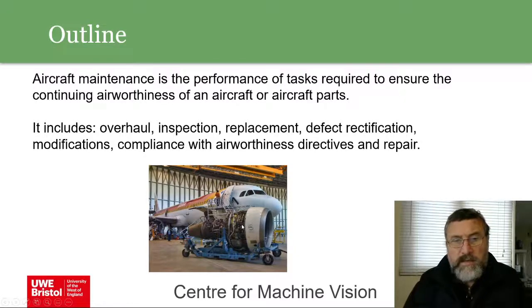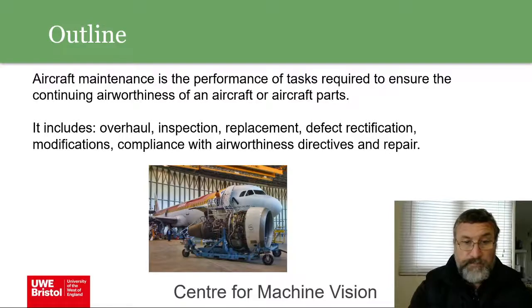Repair, particularly, for example, of aircraft, is a very important area. It must be done to the correct standard, because if it isn't, unfortunately, it can have bad consequences. There are quite a few examples you can find on the internet of where the exact procedures weren't followed. For example, it could be something simple like repairing damage to the fuselage or tailplane, where you don't use two sets of rivets, someone just uses one line of rivets, and that leads to a stress concentration, which can lead to serious things like the tail coming off and loss of the aircraft. So it's very, very important to follow the exact safety requirements on these procedures and standards.